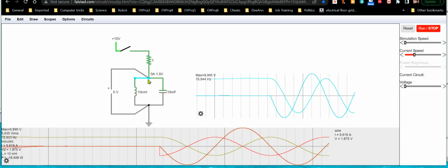All right, but here's where I'm measuring current. So I'm measuring current from positive to negative. Right. That's what's showing up on here. That's why it's a positive current. If I were to swap the terminals, it would actually be down here instead, and that's not what we're wanting. So I'm wanting to keep this, again, in such a way where it's kind of what you would expect if you set this up on a test bench, sort of, because in theory you could set this up on a test bench. This would be your ammeter. Again, your positive red terminal would be here, your black terminal would be there, and here's a separate voltmeter, with the positive red terminal there and the black terminal there.